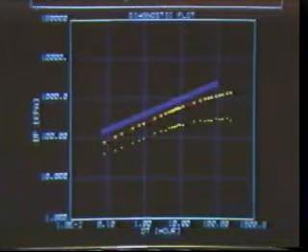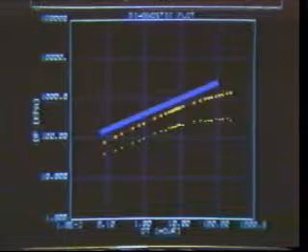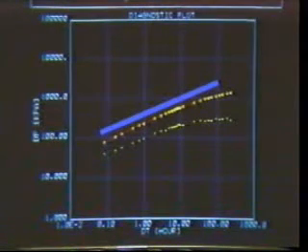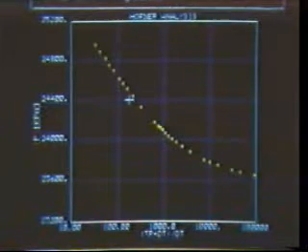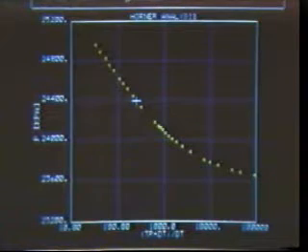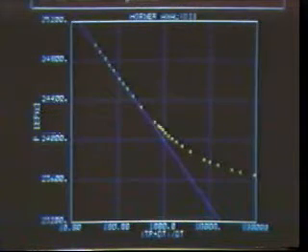We note the presence of half slope, indicating formation linear flow, which should be followed by pseudo-radial flow. The derivative plot supports this conclusion as evidenced by a flattening occurring at the same time. For our Horner analysis, we utilize the specific data points from the log-log plot, which indicate the presence of pseudo-radial flow. Here we define them by using the cursor to create a box, and then instruct the computer to generate the Horner straight line.